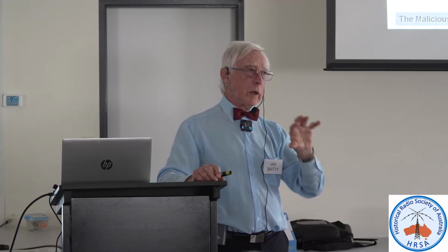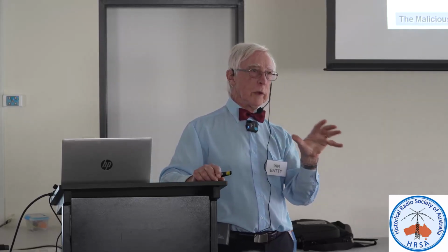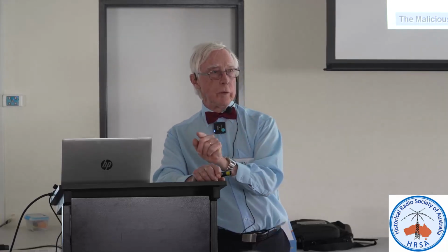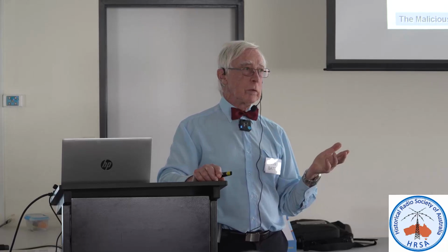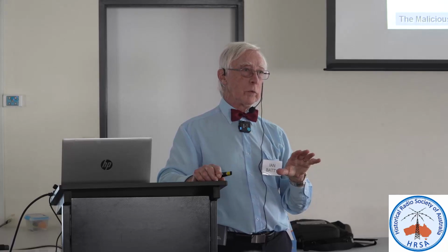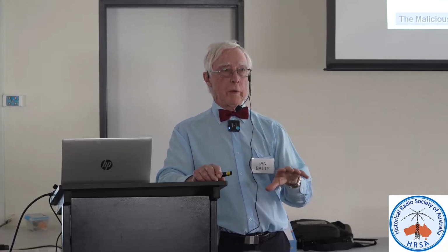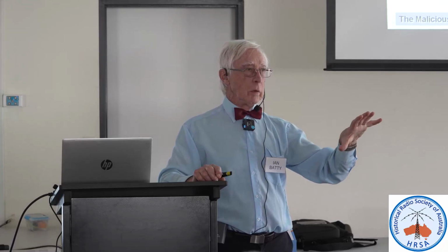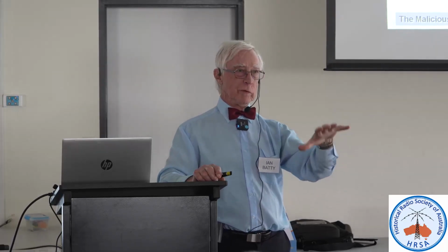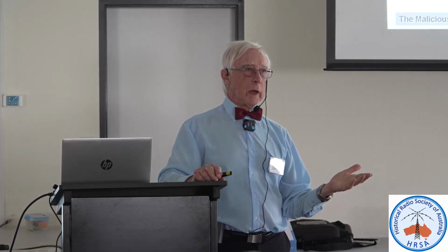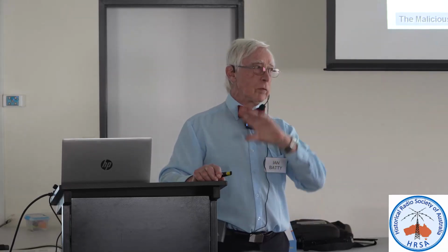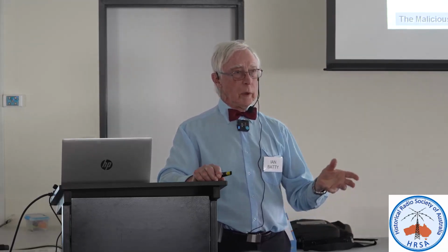I'll bring it up and I should get maybe 20 watts of consumption or less. Remember, this is just the power transformer and the valve heaters. If I get a whole lot more than 20 watts power consumption, I know I've got a fault and it's most likely the transformer. If the set passes that test, I'll leave it on, check it every couple of minutes, leave it on for maybe an hour or so. If the transformer's still just warm to touch, everything's probably okay, and if it had absorbed a bit of moisture, it's on its way to drying out. Okay? Turn everything off, power down, pop the rectifier in, and then bring up the power.